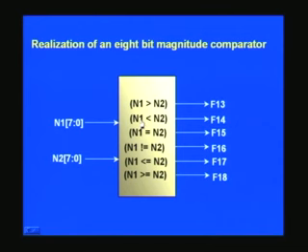Suppose you want n1 less than n2, then activate this output and so on. This is for equality, this is for not equal to, which you are already familiar with, an exclamation mark for inverting, right, and this is the symbol for less or equal to, and this is greater or equal to, and you may get confused with this symbol later on, as they are called non-blocking statements, which will be used in the always block later on. We will see more details later on, and let us see how the program goes.